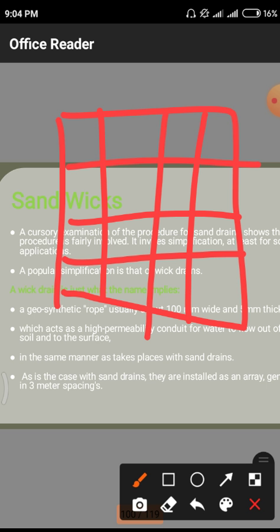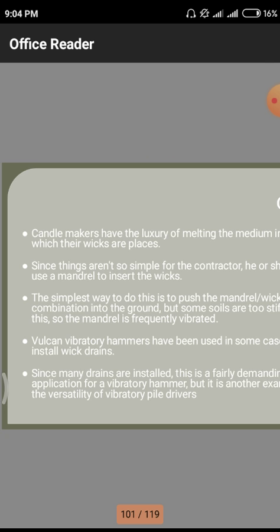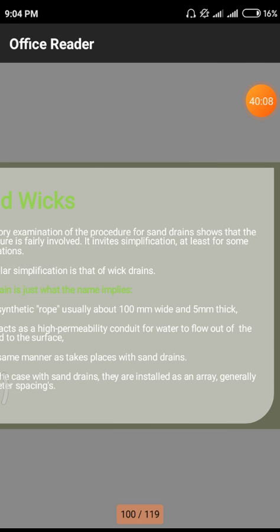But in the construction of these arrays, we need to use slope conditions. Why? Because at the first point in the array we have to use a huge height. At the second point, we need to use less height, so we decrease the height to get flowable properties. If we maintain parallel lines, there may be no movement of water, so definitely we have to maintain some slope to drag the water from one point to another and another.